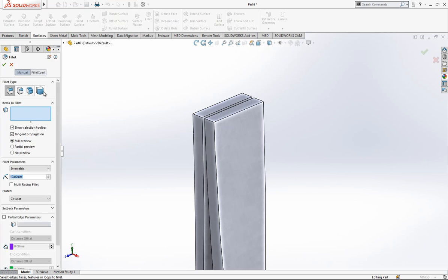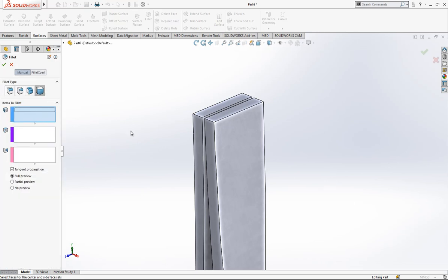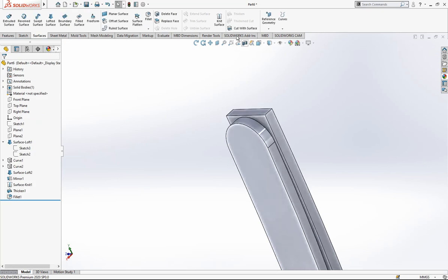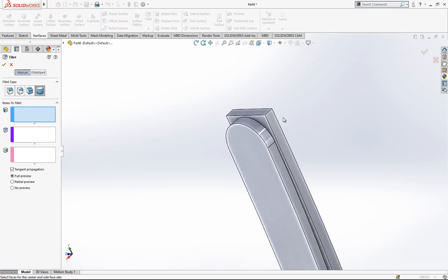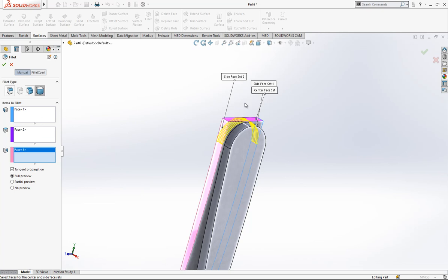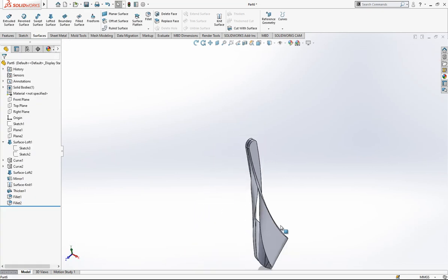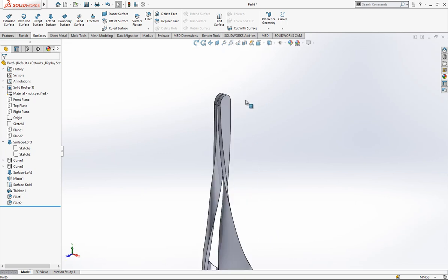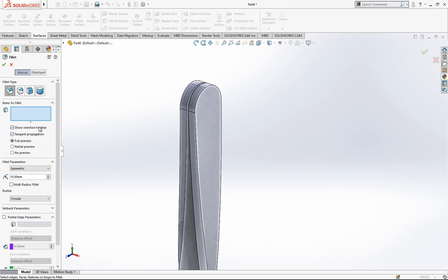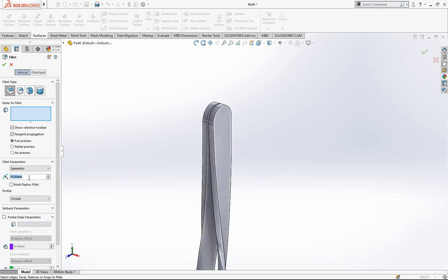Then we make a fillet with full round fillet. We select 3 different surfaces, which should be successive. We create here one radius, like we round the edge. For each box you need one object, and once you are done with this, you can go to the next step, adding fillets on it. This will be a normal fillet operation, and radius 0.1.